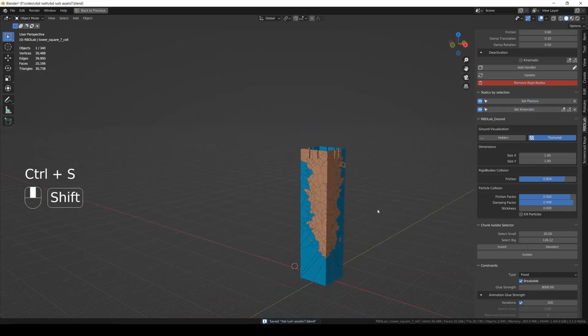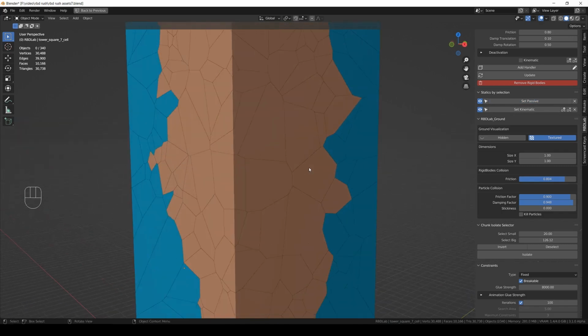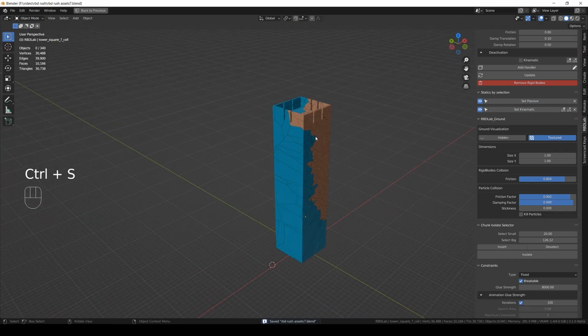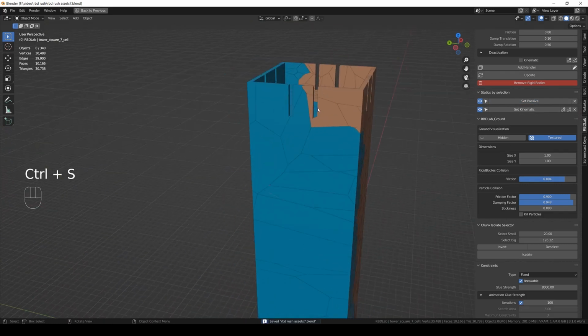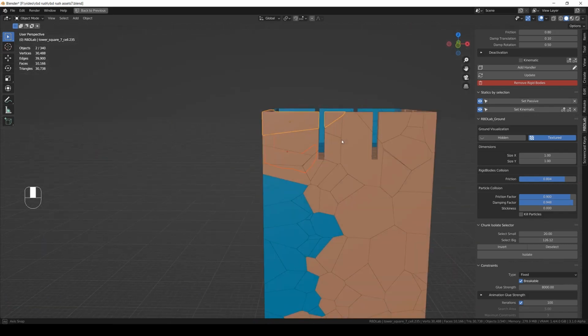Actually, where is this piece going? Little piece of rigid body. Be passive, please. It's very normal that complex geometries give some unrealistic fractures in complex parts like this corner. If you don't want to see these pieces moving, just set them on passive.